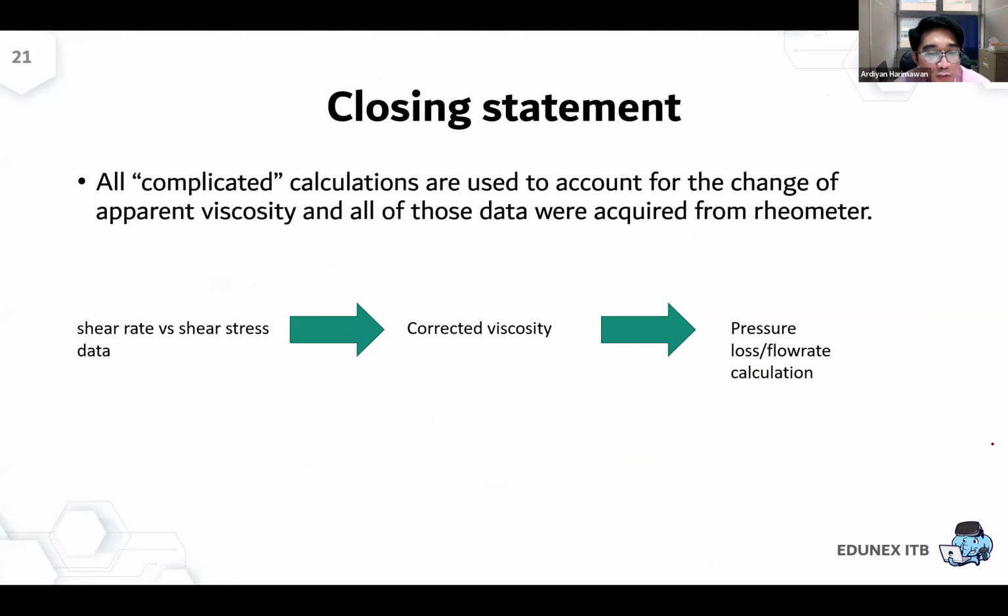To close this subject, for third semester chemical engineering students, the non-Newtonian topic is just the introduction. I think you can differentiate the behavior differences between non-Newtonian and Newtonian, both in physical appearance and in mathematical formulation. If you flow a non-Newtonian fluid, there are corrections on how to calculate Reynolds number, friction, and energy loss. But once you have the energy loss, putting it into the Bernoulli equation is the same as Newtonian. It is just a bit more complex in calculating parameters that require viscosity, because in non-Newtonian fluids the viscosity is not always constant along the time, along the way, along the force.